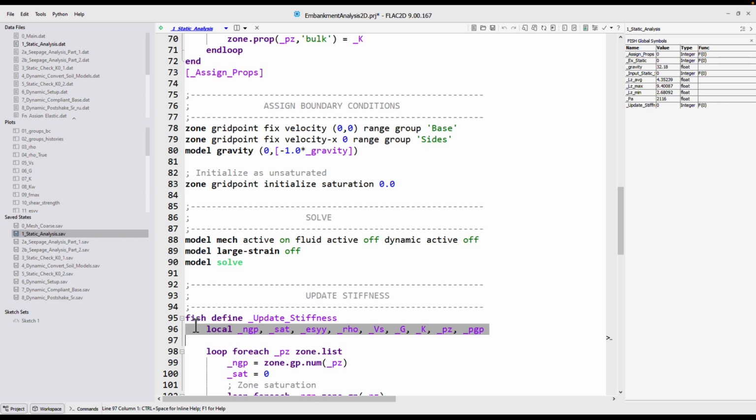There are several reasons for doing that. At least one that comes to mind is that when I want to check the values of these variables, I'm not going to want to have 100 different FISH symbols to keep in mind. Also, there could be some unknowing negative impacts of a variable defined as global then affecting something subsequently in my code.